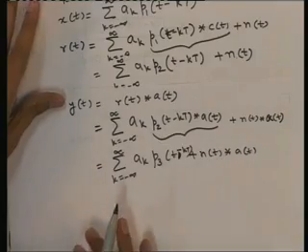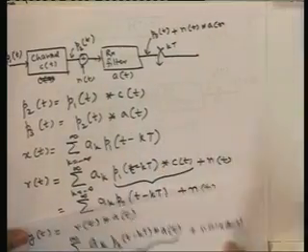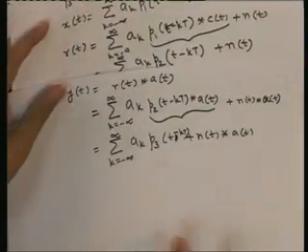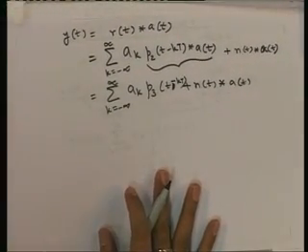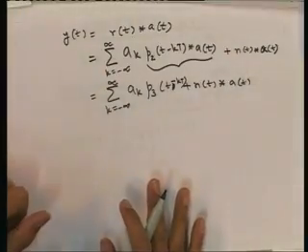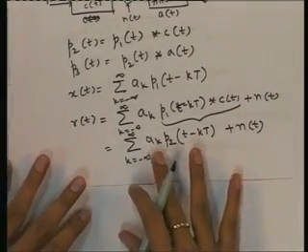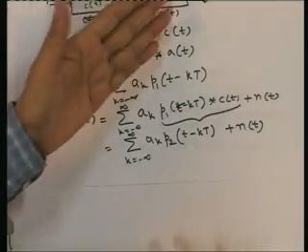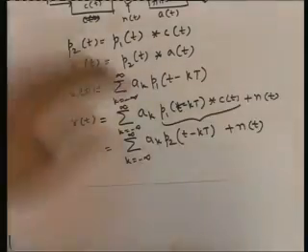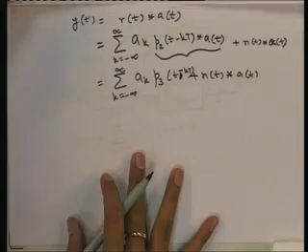so this is also like a PAM signal with a different pulse p3(t), plus a noise which is not white noise now. So now what we are doing is sampling at multiples of time T. We will sample at T, we will sample at 2T, and so on. We will now see what we get if we sample. Now on all of this we have made no assumption that p1(t) is real or anything. p1(t) can be complex, c(t) can be complex, a(t) can be complex, noise can be complex, everything is complex here. If it is real, it is a special case of this.